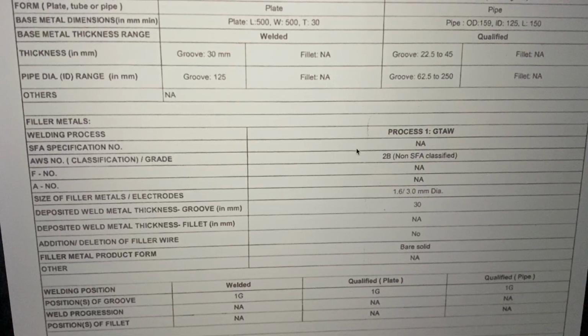So accordingly, this range can be overwritten by us. It is not that the code says you can go to 1.5 times the qualified thickness, 2 times the qualified thickness, or half of the qualified thickness, but we are the boss when we are writing it, and we can surely stay within the range but squeeze it and make it more stringent. The next is consumables, which is covered in our filler wire, filler metal.